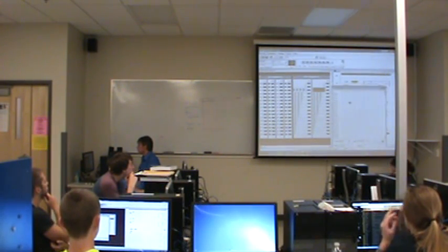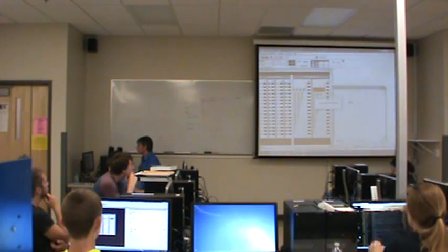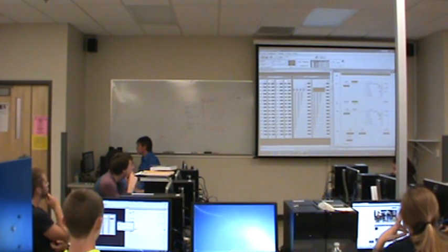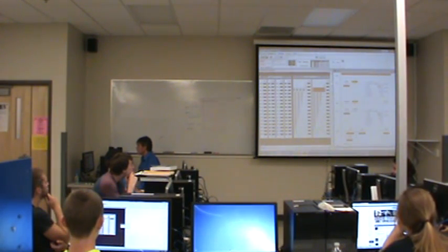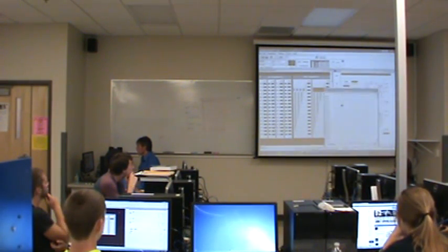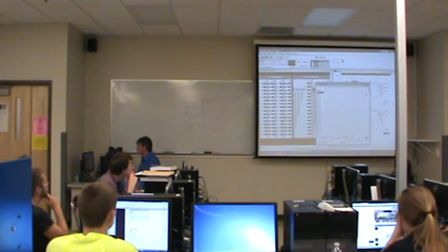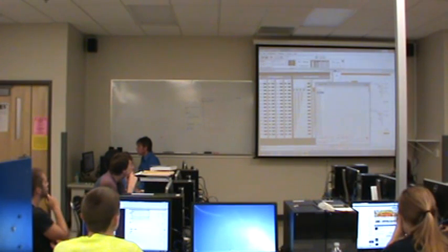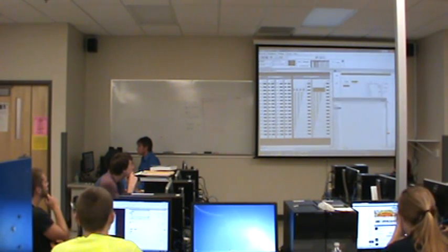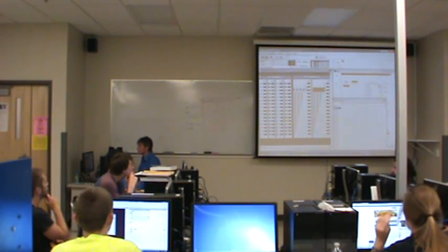All right. Download, run. Okay, what is it looking for first? It wants to see the inputs look like this. It wants to see bit 0 come on in input 5. So let's do it. Turn bit 0 on. Well, we'll increment this. So there it is. Came on.